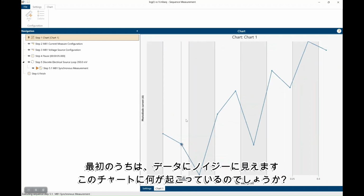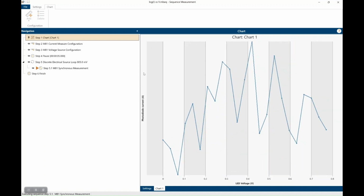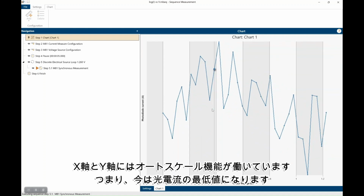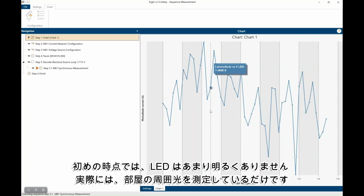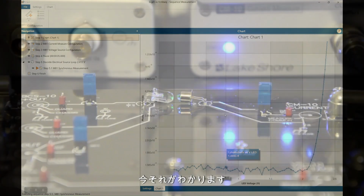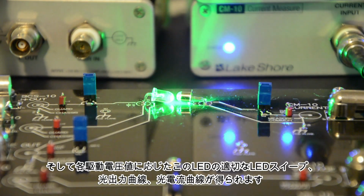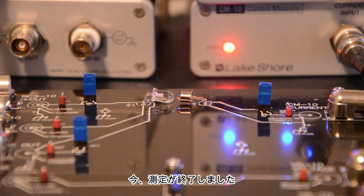So at the very beginning, you'll notice that the data does look noisy. What's happening? The chart X and Y axes are going to auto scale. So we're at the very low end of this photocurrent. The LED is not very bright at this point in time. We're actually just measuring ambient light in the room. But as the LED begins to get brighter and brighter, it will start to auto scale, and you can see that now. And so we'll get a nice LED sweep, or light output curve, or photocurrent curve for this LED at specific drive voltage values. And now we have completed that.